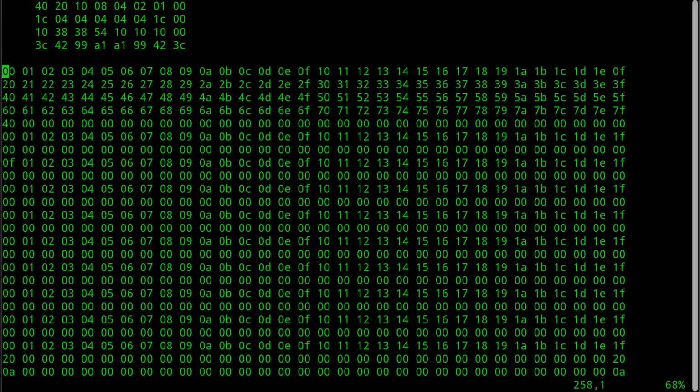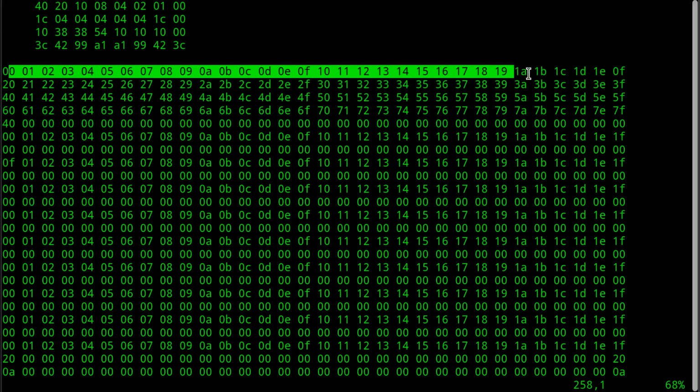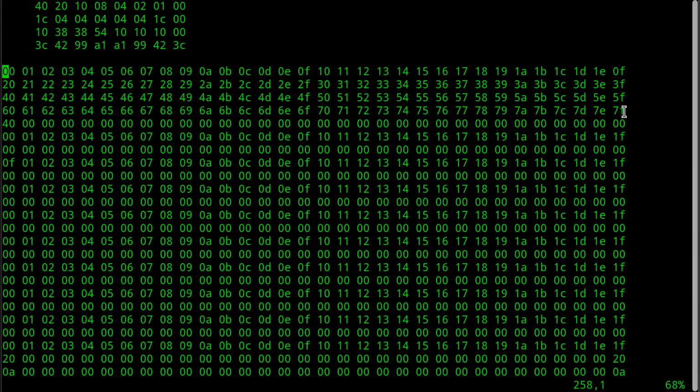This then is the name table data, and this accounts for all the bytes that go into the VRAM, and I configured the configuration registers so that these tables start at these various offsets, or where the bytes appear in this initialization data file. So if you look at the name numbers, the pattern numbers, for each one of the positions on the screen, you'll see they start and count 0, 1, 2, 3, 4, 5, yada, yada, yada, and they count up until you get to here, and then they, I don't know, do crazy things.